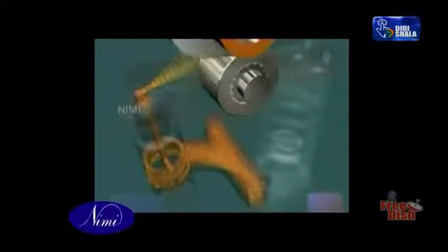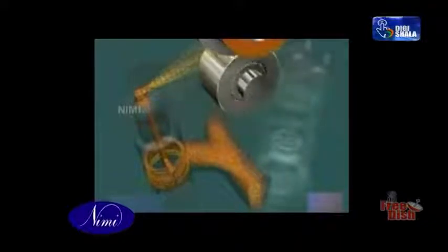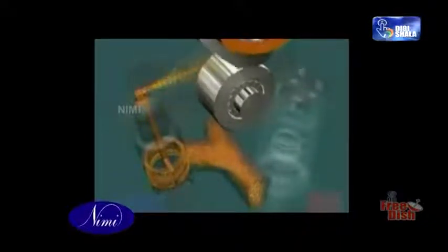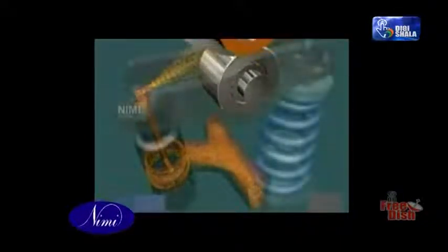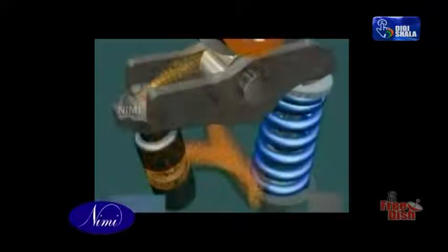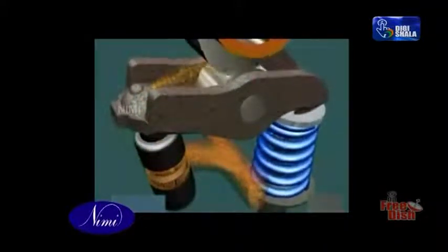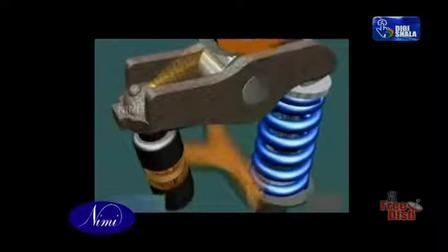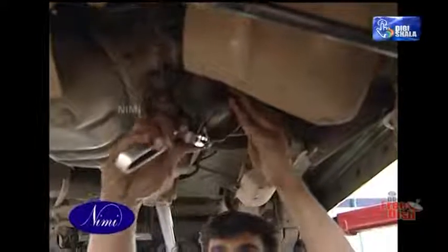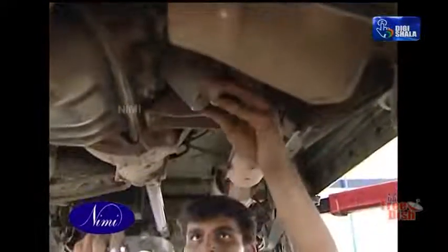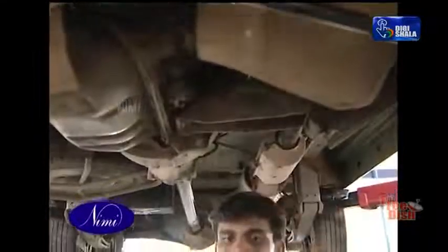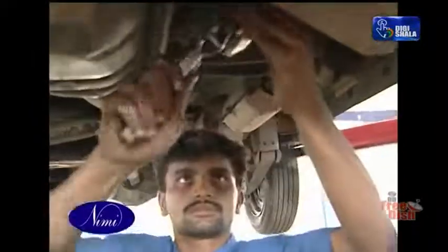Relief valve. Generally fitted in the gallery, this spring-loaded valve opens when the pressure reaches the maximum limit. Filters. Screen that prevents the pieces of metal entering the pump. There is an external filter which can be renewed periodically.